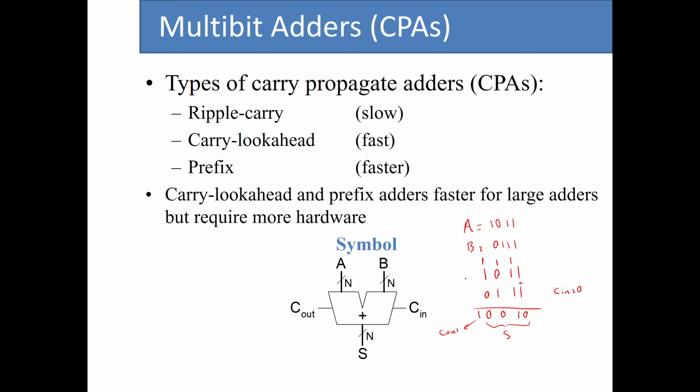But for the other ones, we definitely needed a full adder, because we had to find out the result of adding 3 numbers: the carry from the previous stage, the corresponding bit from the first number, and the corresponding bit from the second number.